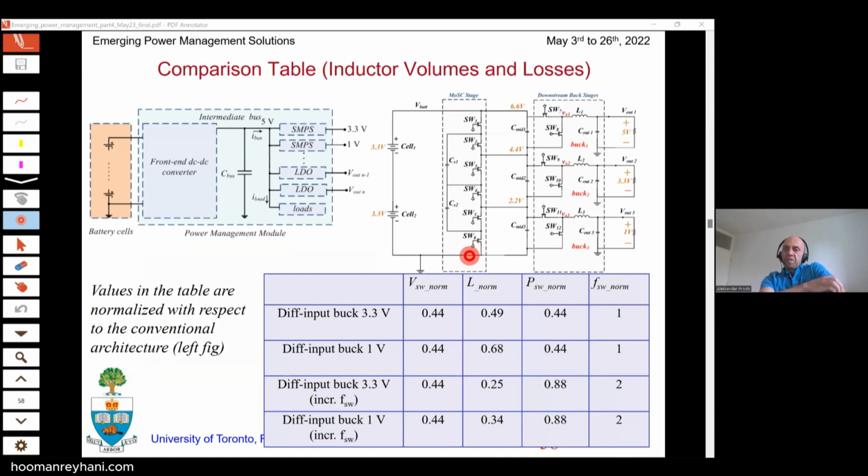Basically, now if you think about these transistors, they can be rated for much lower voltages than the transistors that need to run at the full swing. Meaning that, by the fact that they are transistors rated for lower voltages and practically the same current, we already have smaller R-on resistance.